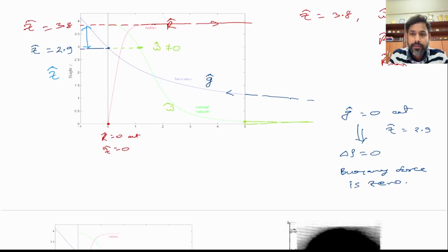not buoyancy flux. Okay, and as you go further up, obviously the g prime goes negative, and then the momentum becomes zero, and beyond that point there is no force for the plume to drive further up, and that is the point at 3.8 where the plume completely stops.